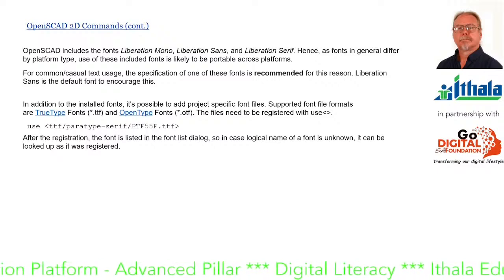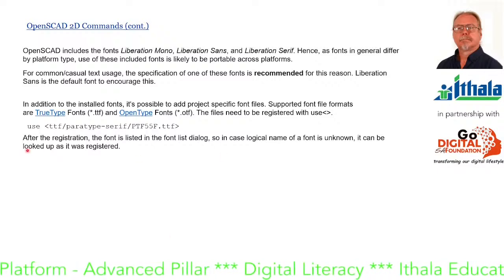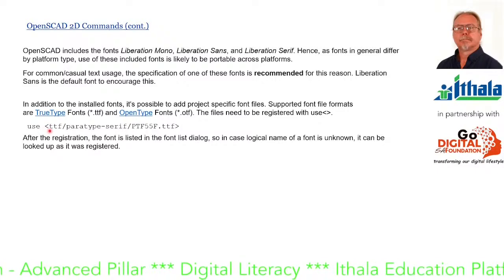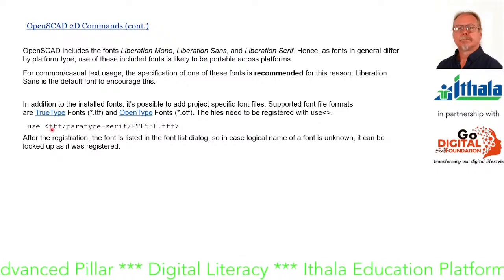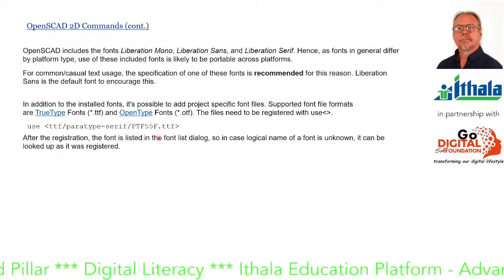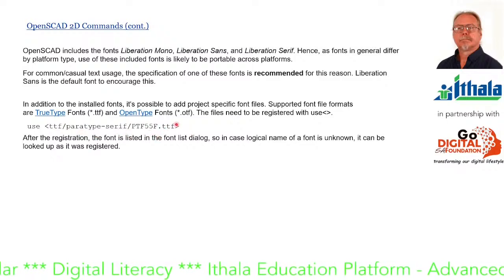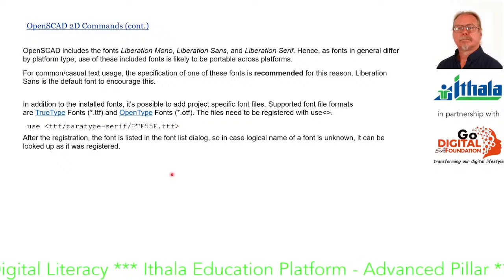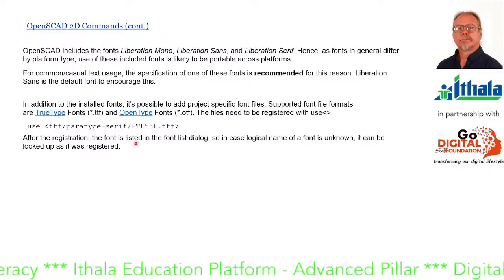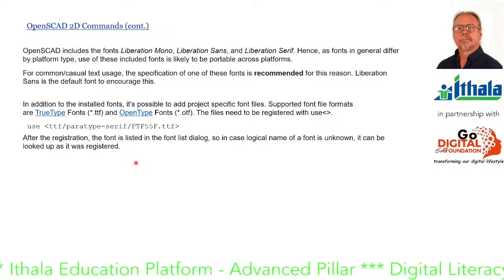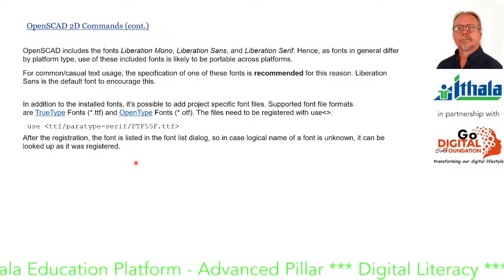Okay, so if you want to use a funny font, then you say use and in these brackets, so less than sign, ttf/paratype serif, like that, and that's the name of the file, and close the brackets with a greater than sign. That registers the font with OpenSCAD, and then the font is listed in the font list dialog, so in case the logical name of a font is unknown, it can be looked up as it was registered.